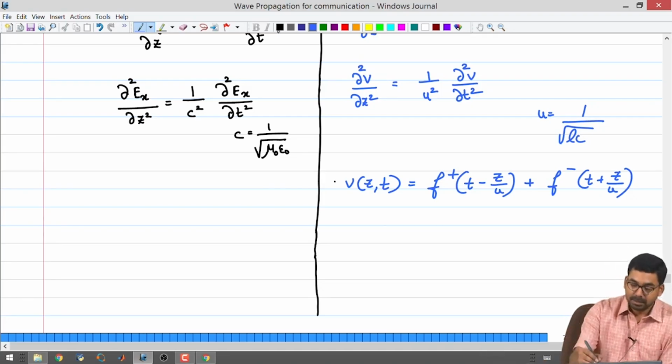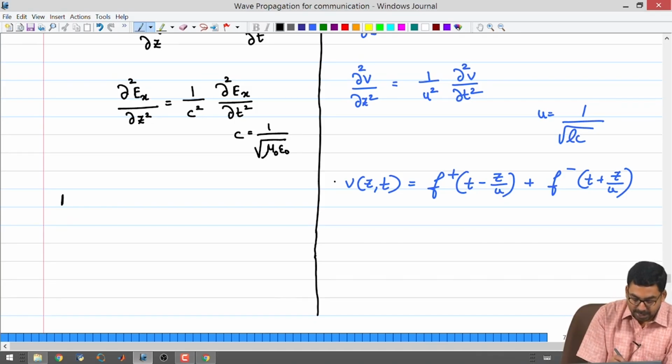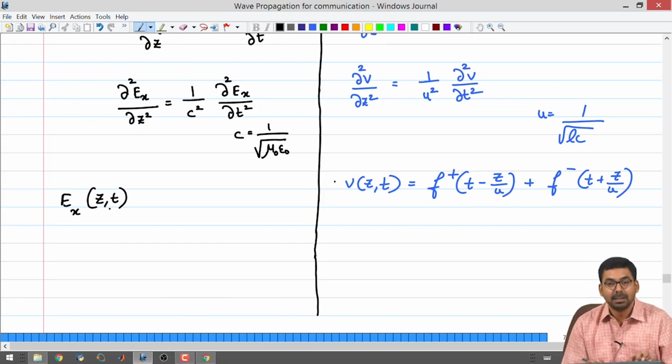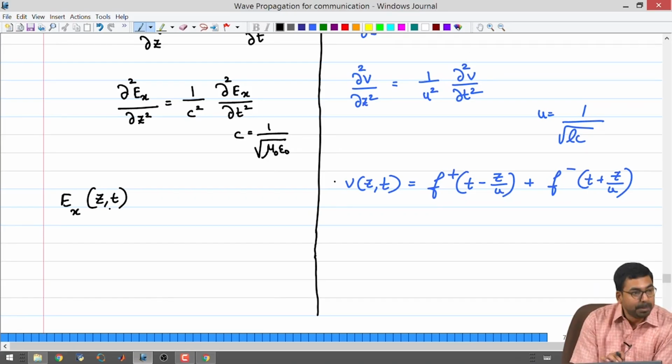On the left hand side, the solution Ex is going to be varying in z and t. This is something that students have difficulty with. Sometimes they get confused because they put the subscript x, and then write it as x comma t. This is something that you have to remember: because I substituted Ez for a z direction propagation, it will not create a time varying magnetic field. This is a common mistake and it happens for many people.